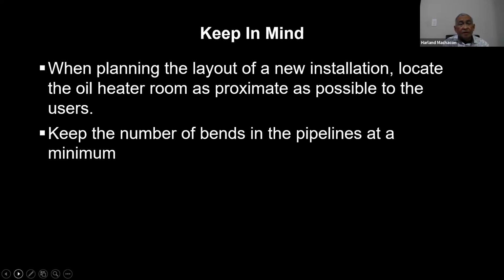We also keep in mind that when we plan the layout of a new installation, make it a point that the oil heater room is located as proximate, as close as possible, to the users. So you will have a shorter run of pipe and a lesser head loss. And of course, keeping the number of bends in the pipelines at a very minimum.